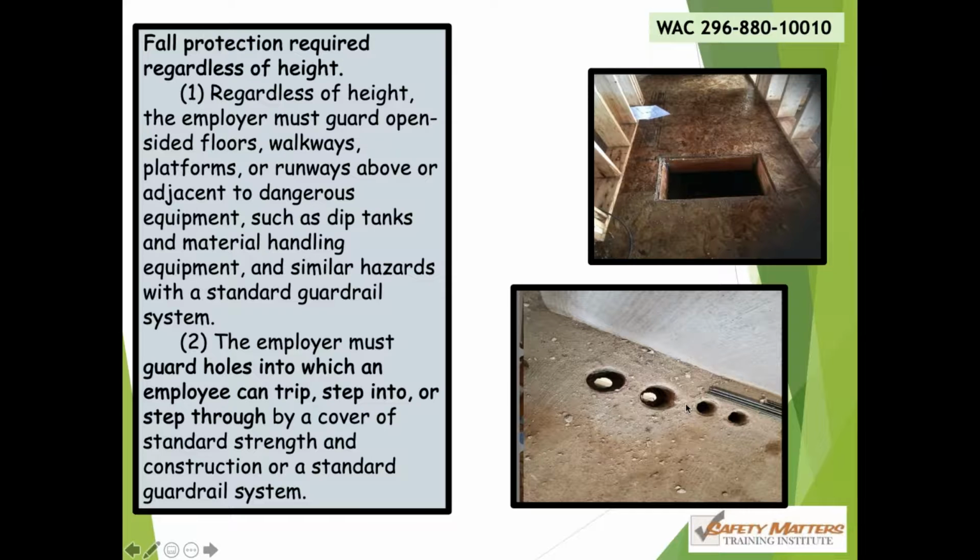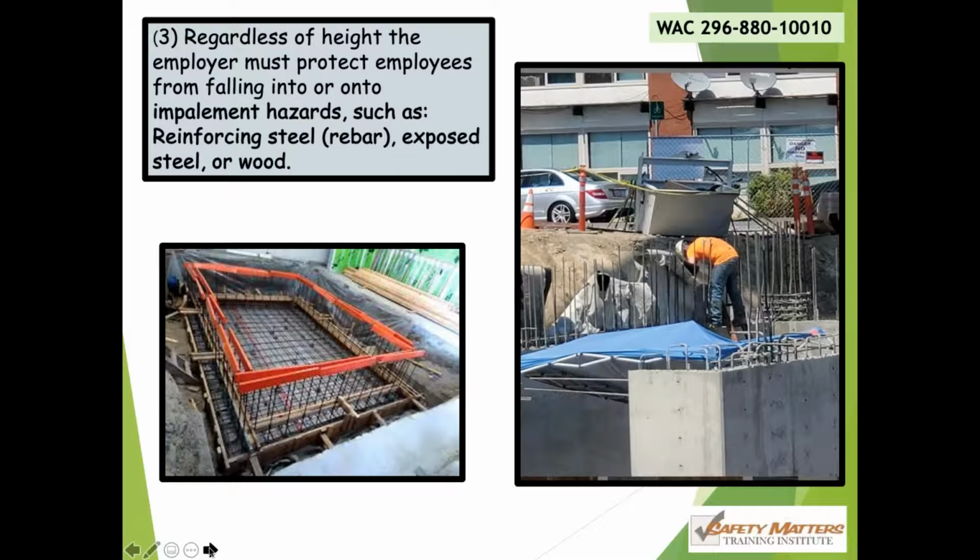These little holes down here, these are plumbing holes, right? Well, they're of various sizes. I've got a small little female foot. This is a 5-inch core hole. Guess what I can step into, trip into, or step through? I can step through one of these things. I can certainly trip into one of these things. So these need to be protected. We need to be guarding these things out. It's not new that we have to protect the holes. It's new how they describe them. We can trip, step into, or step through a hole.